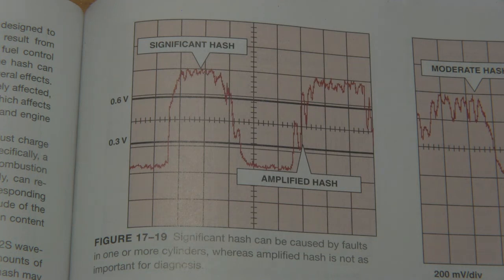It can be due to an injector that for a moment got stuck and maybe didn't quite open all the way, which might be an intermittent issue. You might have a fuel rail that's partially clogged, low fuel pressure, a clogged fuel filter, or a fuel pump that's going bad. Lots of things can cause a lean misfire.